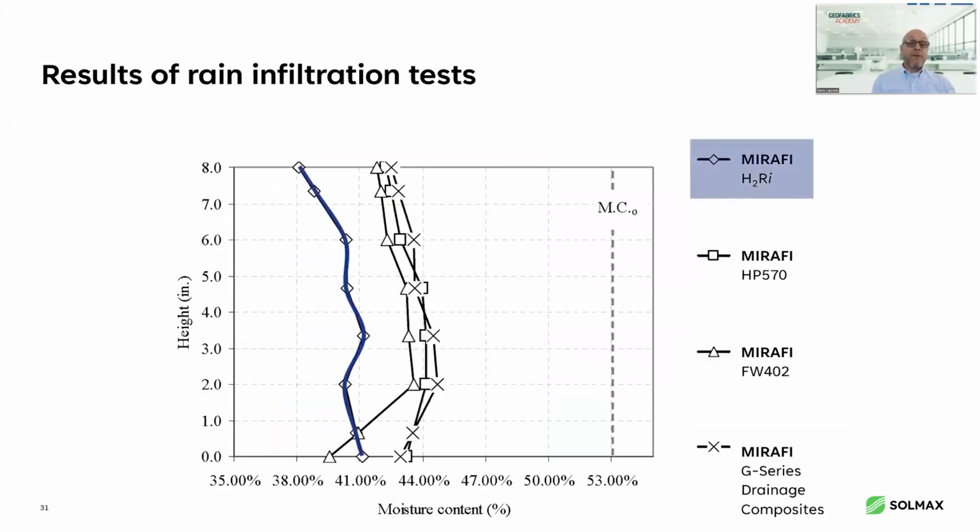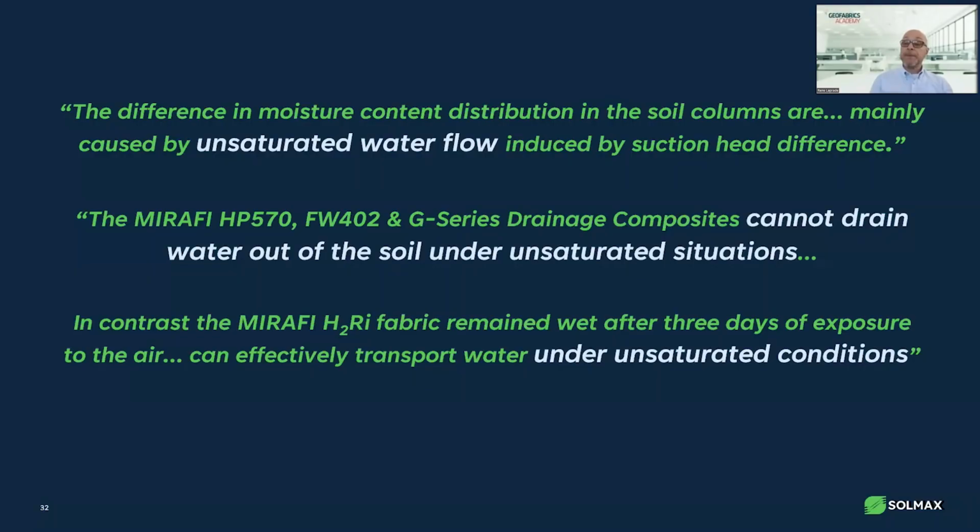But what they found was that, in fact, the ELDG provided more drainage. It provided anywhere from 3 to 6% more moisture removal than any of the other products, including the geocomposite, which is a very large opening drainage product. And so it can certainly move a lot of water, but it wasn't moving more water than any of the other products, except for the ELDG.